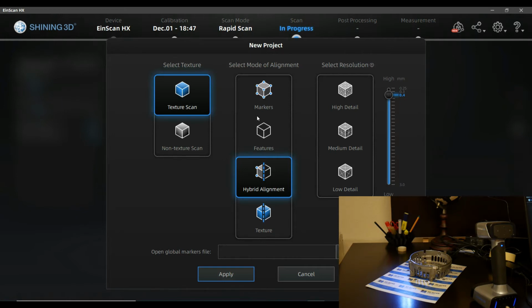So to know where to put that new scan, the next frame, and the next and the next frame too, you have different possibilities that you can use to give it that orientation. First is markers. As you can see, markers on the part itself have a function similar to the stars in the sky, for example for a sailor orientating himself on them in the night, and the scanner can see those markers, and it knows at first where they are.